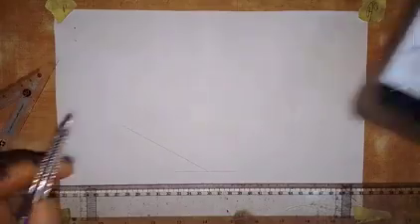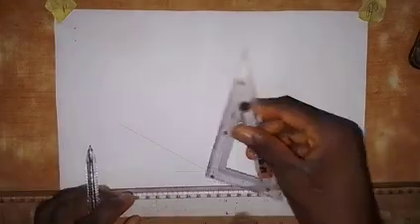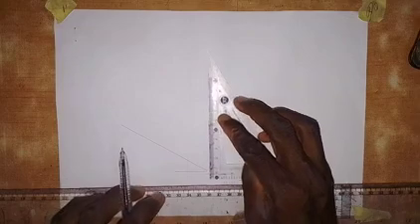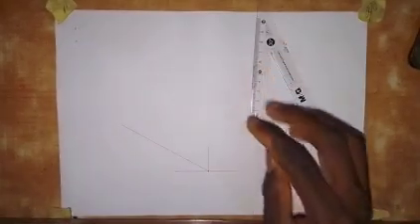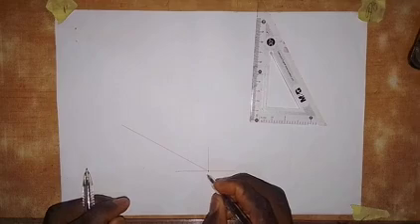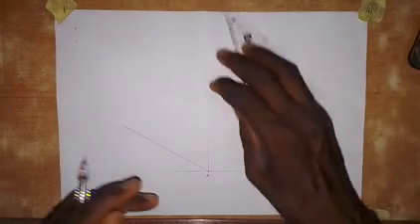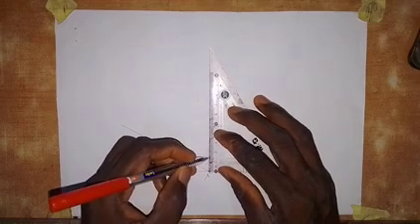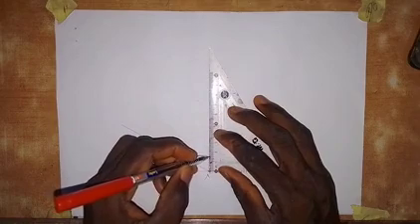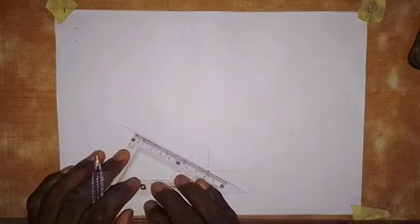So what I'm going to do first is to produce this shape here, as we see it here. So that's the first thing I'm going to do. Coming to this point here, I will draw a vertical line like this. So this is the lowest point, so I will write lowest point A here. So I'm going to take a measurement of 15 millimeters up this line from this point A, 15 millimeters. And then here on this side, I'm going to take a measurement of 80 millimeters.